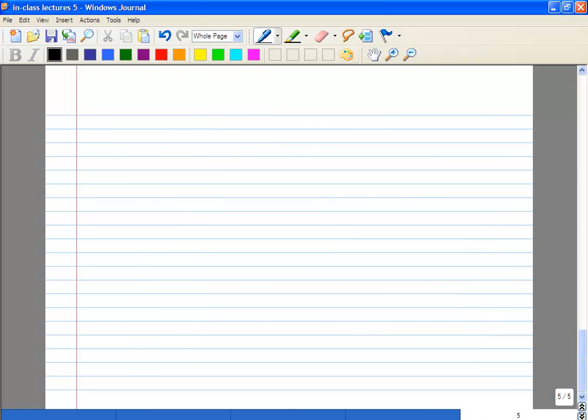Okay, so let's look at what kind of capacitances you have. You're interested in, let's say, drain bulk and source bulk capacitances. The other things, for example gate drain and source drain, are all related to your gate drain or gate source overlap capacitances. So you can't do too much about them. That's limited by the process. But the junction capacitances, you can do something about them. If you look at these junction capacitances, they actually have two components.